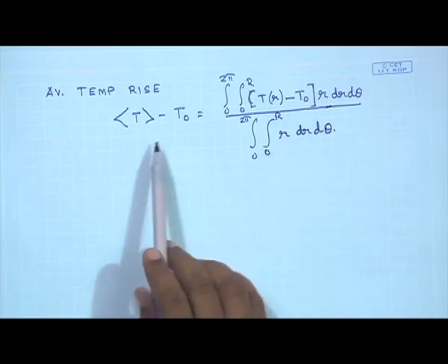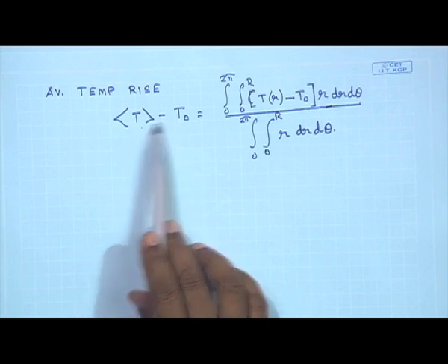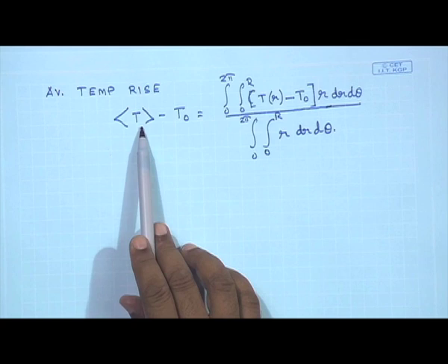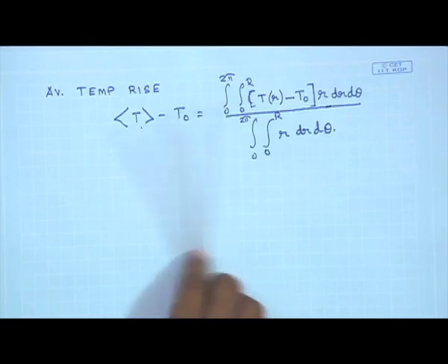So this is a standard method of expressing the average temperature, the same way we have expressed the average velocity when I have a parabolic distribution of velocity inside a pipe due to, let us say, an applied pressure gradient, and the liquid follows a parabolic velocity profile.